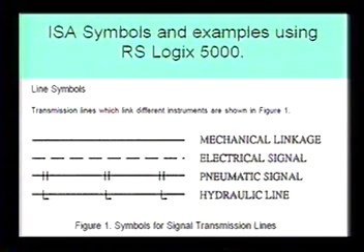And once the flow diagram got approved by the client, then we took that flow diagram and converted that into the PLC and the control panel design. And so my point is the flow diagram actually is the lead document. Once you get the flow diagram defined, then you can start building all the process and the actual skids and everything, because now you know what you're going to do.